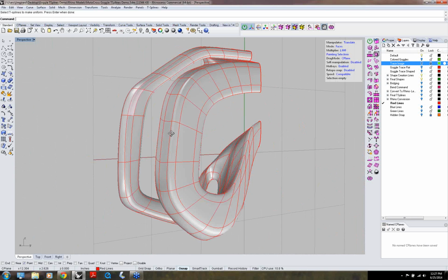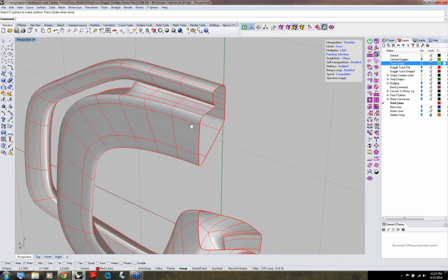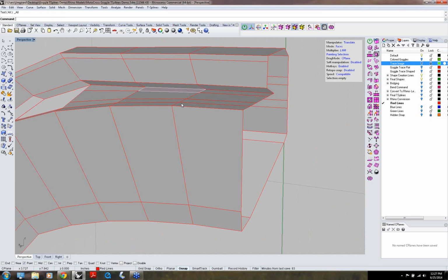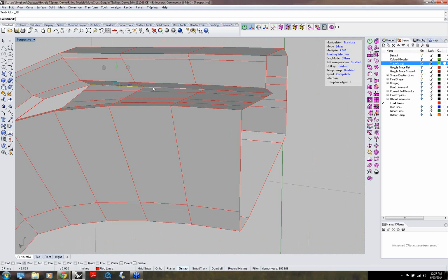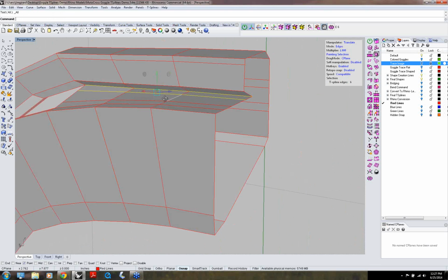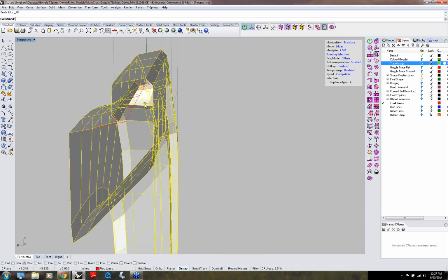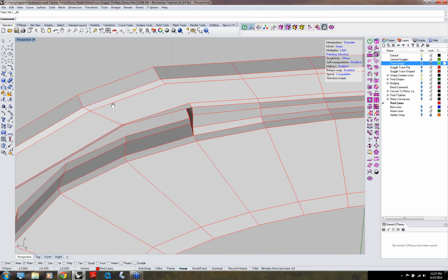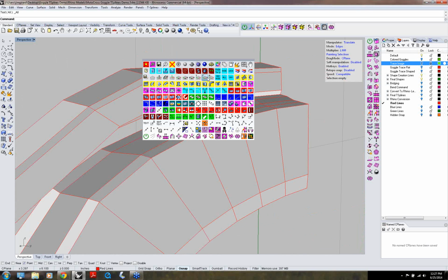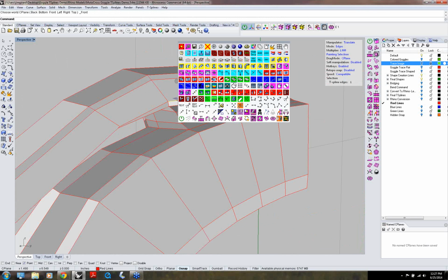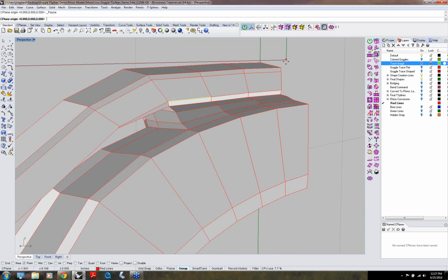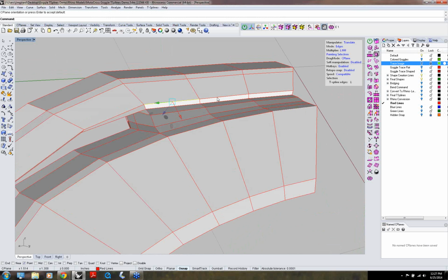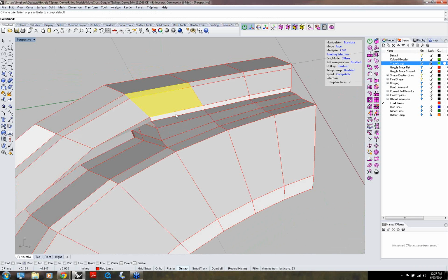There's some really nice things going on. Again, you can go back to your box mode, and you go to your edge mode. Say you want to make this a little bit, you don't want to undercut there. Now you can just pull those out. And what I tend to do is I'll come over here and go to my front view, and then I'll pick 2 points for my front view. I'll pick that point and that point. Now it's laying there. And then I'll just grab all these surfaces.